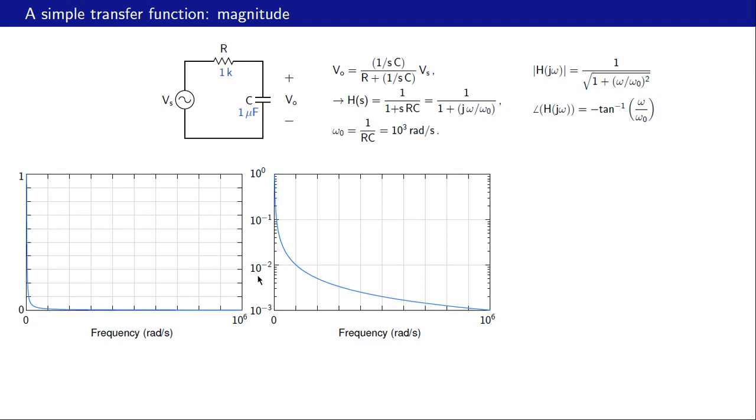For example, let us take omega equal to 2 times 10 raised to 5 radians per second, that is here. And now we can read the value of mod of h from this curve. So somewhere there. What is that value? So this is 2 times 10 raised to minus 3, 3, 4, and let's say it's 5. So something like 5 times 10 raised to minus 3. This was not possible to do in this older plot because the y scale had also got compressed here.